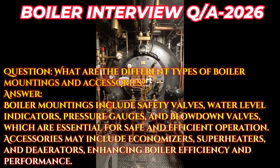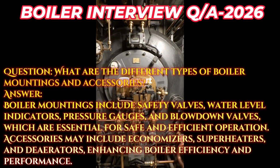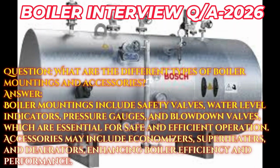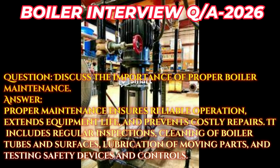Question. What are the different types of boiler mountings and accessories? Answer. Boiler mountings include safety valves, water level indicators, pressure gauges, and blowdown valves, which are essential for safe and efficient operation. Accessories may include economizers, superheaters, and deaerators, enhancing boiler efficiency and performance.